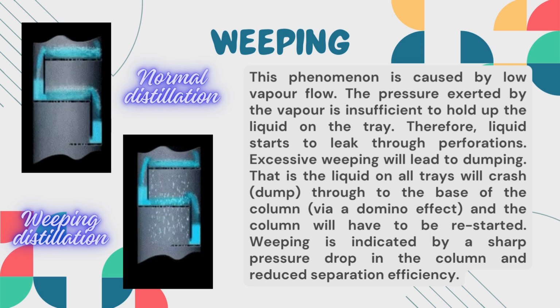In simpler terms guys, weeping is the concept in distillation which refers to the phenomenon where liquid droplets are carried over from one part of the distillation apparatus to another. Typically, it occurs in the column of a distillation setup where the separation of the components takes place on their boiling point. Guys, weeping can occur when the vapor rises through the column and condenses into liquid droplets before reaching the condenser. These droplets fall back into the column, impacting the efficiency of the separation process.